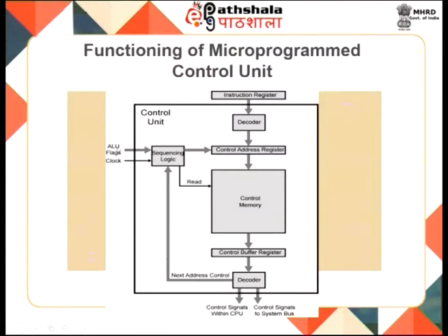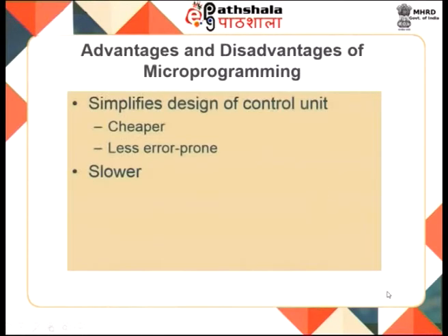Based on the flags, your ALU flags, your sequencing logic decides which instruction is to be executed next. That is given here to the control address register. Your control memory is addressed, you have the control words, and the control words may have to be decoded, and all the control signals get generated. If you look at the advantages and disadvantages of microprogram control, it simplifies the design of the control unit.